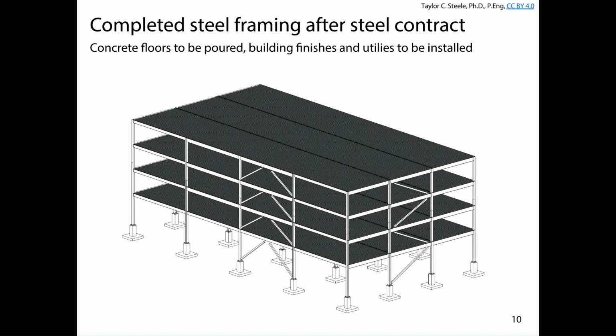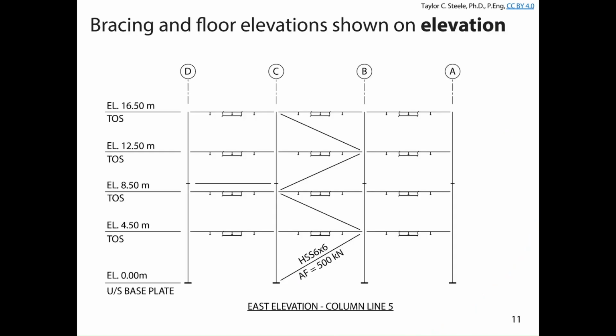And what I'm going to show you is how we represent the bracing arrangement on this face here, right? You can see there are some diagonals between beams and columns on that side. There are some diagonals between beams and columns on this side. If we wanted to communicate to the fabricator of record and the general contractor how that's going to be arranged, we would draw that in 2 dimensions, something like this. In this drawing, we've got several different pieces of information.